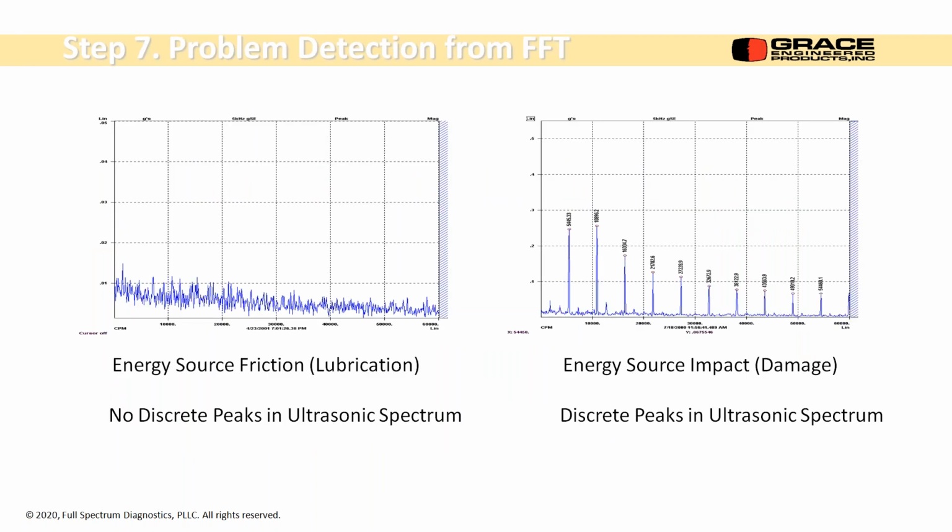These are the two things that you'd see in the spectrum. So you can do a spectrum of that sawtooth waveform. And if there's no sawtooth peak in there, there's just noise floor, random noise, you'll see something like that. So every survey, this will go up and down a little bit. We can trend the overall level of that energy.